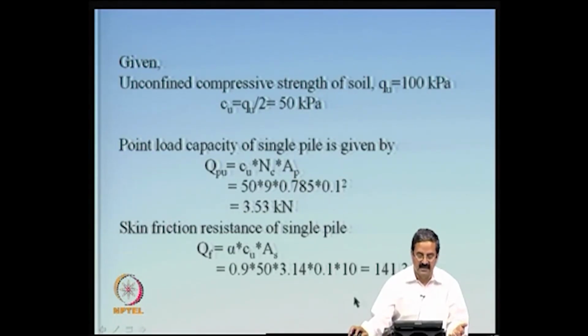But here the pile diameter is smaller and this one dominates. So, what I want to highlight is that if you have small micro piles which are easy to install, they can take care of the carrying capacity of the bigger pile itself, and the advantage is that it is very fast, convenient, and quite easy to do.